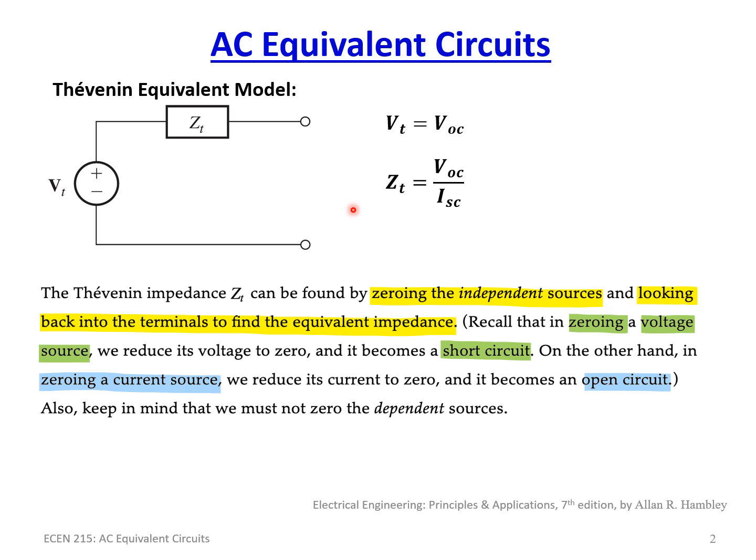And if you have a power supply that has become shorted in the case of a voltage source, the equivalent impedance of that is a 0 ohm resistor. There was some confusion on some of the tests and homework: once I short it out, what happens to all the other components down circuit that are also in parallel with the voltage supply? Well, that voltage supply is shorted. All those other components are now in parallel with a 0 ohm resistor effectively. So there's 0 ohms. They're now wires.